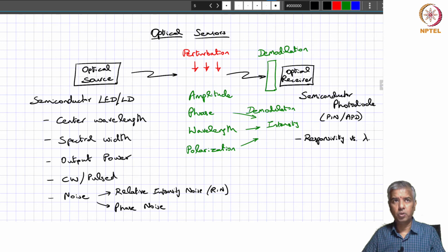Similarly, if you want to go to near infrared wavelengths, say 1 micron and above, what material would you use? Well, the most popular material for those sort of applications, especially from a communications viewpoint, is indium gallium arsenide, right? So each of these would have their own responsivity curves as a function of wavelength. So that is clearly one major aspect that characterizes these semiconductor photodiodes and the corresponding optical receiver.